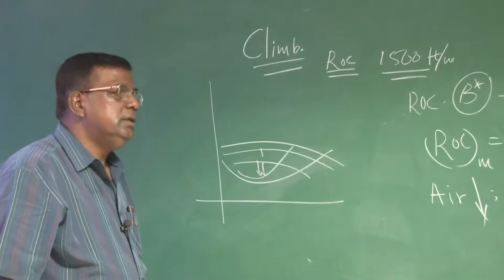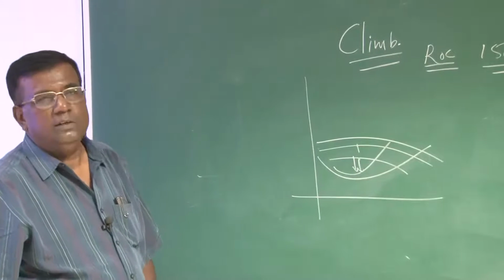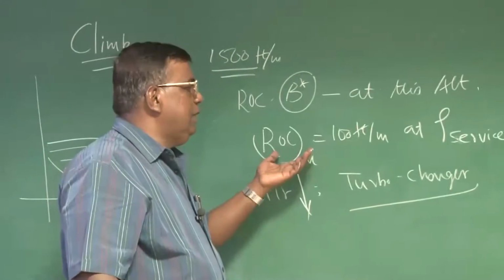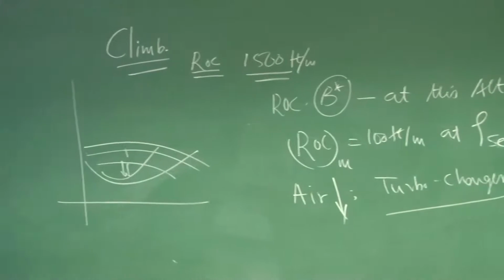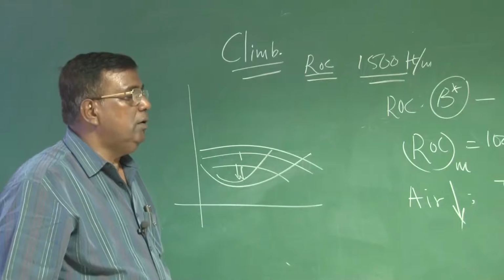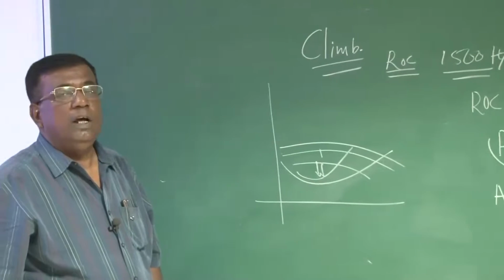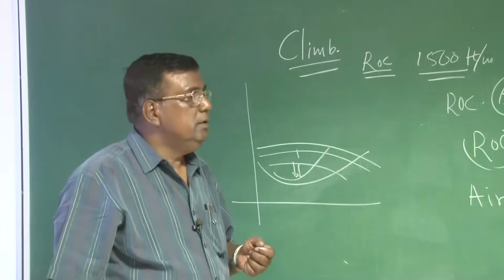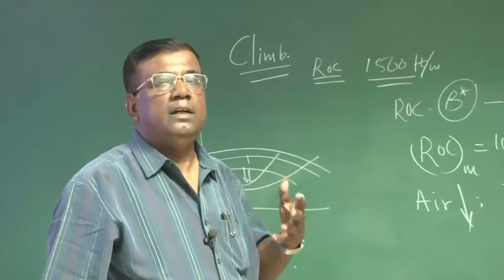However, this costs money, right? Efficiency goes down. But yes, we have to go to that altitude, so there are provisions of turbocharger, supercharger, etc., associated with the engine. That not only helps in getting a good service ceiling, but also creates maintenance issues. You have to be very particular about it. Apart from that, beyond an altitude for a non-pressurized airplane like Cessna 206 and all, you need to ensure that there is an amount of oxygen in the cabin so that pilot and passengers are comfortable, right? So you will find many such altitudes people are flying, the pilots and co-pilot combination are flying, they carry oxygen cylinder, oxygen mask with them, right?